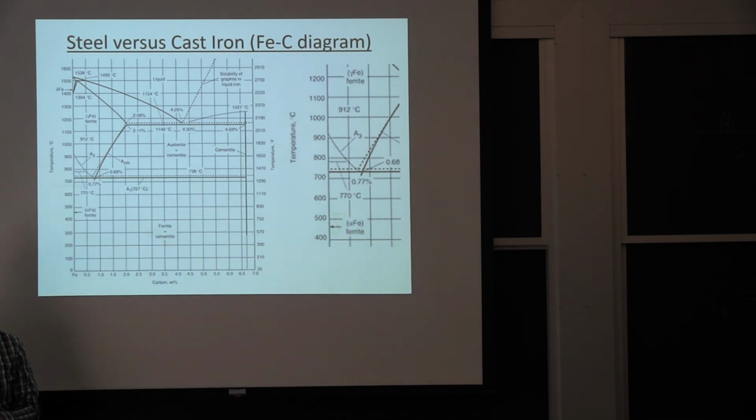So it's not a perfect world. There are a lot of trade-offs, and what I also want you to keep in mind, and we'll go through that in details next week, is there are very, very few pieces of steel in the market that are quenched steel, that are martensite, because it's too brittle. But it's an intermediate step to go to a good compromise in microstructure. So you start with something soft, you make it very, very hard, and then as we'll discuss, you heat it up again to get the compromise. And that's what we call high strength and super high strength steel.